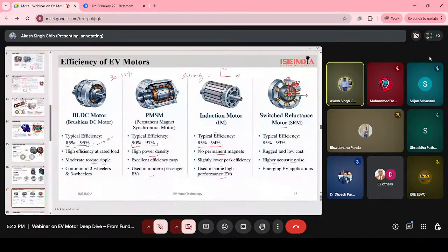If the rotor gets aligned with the rotating magnetic field, then how will it move forward? It needs some difference to rotate, to generate the torque.